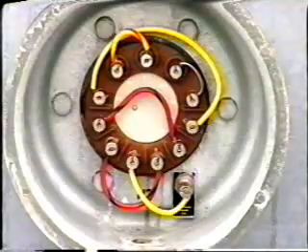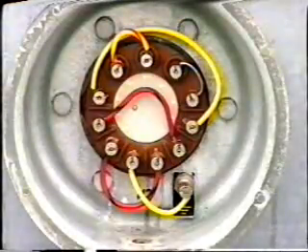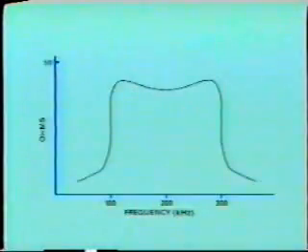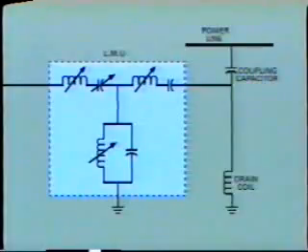Connections between the many inductors and capacitors are made at the terminal board by metal conductor straps. For this reason, the initial test and tuning is often known as strapping. In yet a further development, the tuning circuit is designed to allow operation over a wide band of frequencies, say 100 to 300 kilohertz. Simplified, the circuit looks like this.